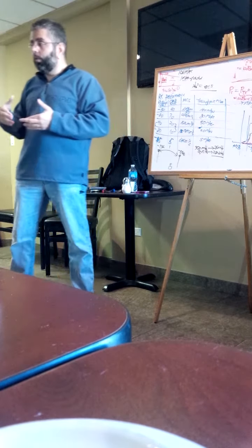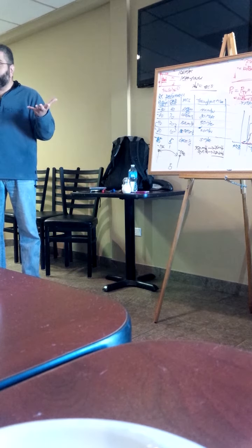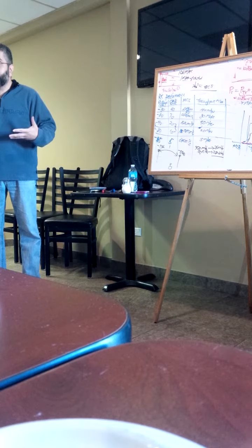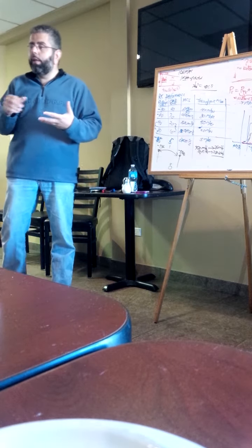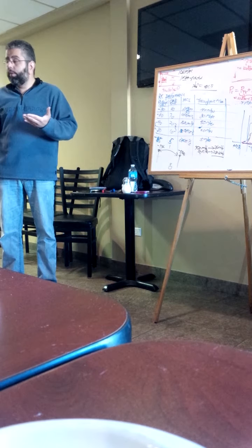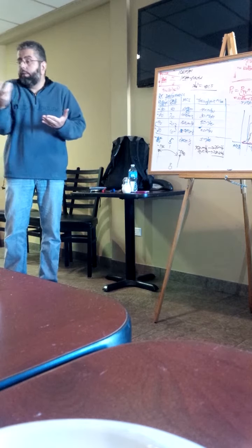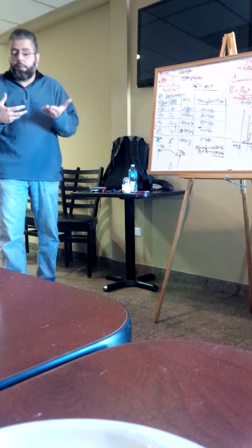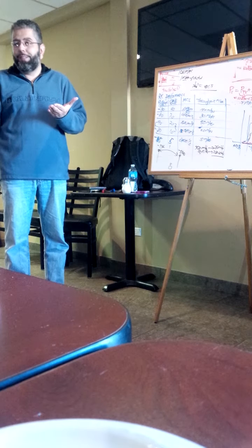They could do something even more sophisticated. They could keep track not only of the power, if they wanted to, but they can keep track of the MAC addresses. Since this is their own system, they can say, okay, I heard MAC address X, Y, and Z. He was at this level. These guys don't move. This is a fixed network. There are no handovers, right? These are fixed devices. There's no mobility here. So if I hear this power from this guy, the only thing that can change is foliage.